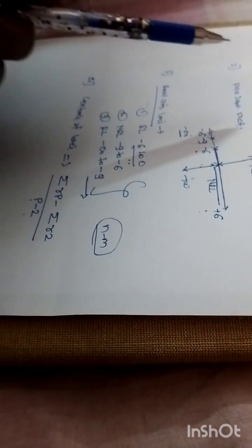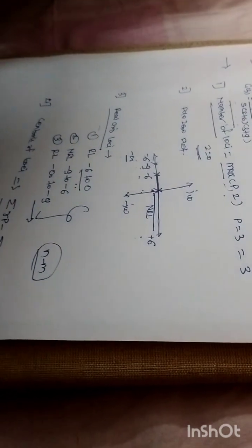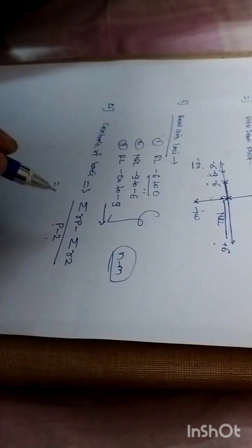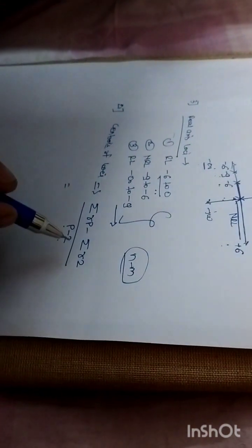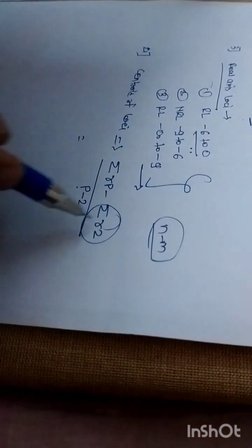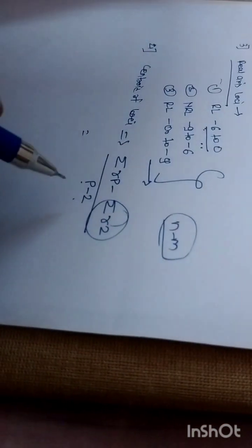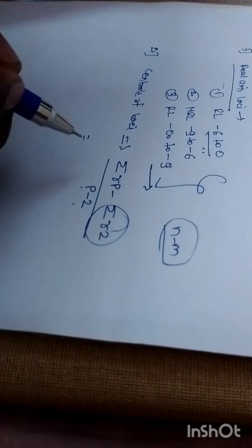Now currently in this example, this is the basic one. We don't have imaginary poles. We have only real poles, right? So this centroid will become what here? Summation of real part of poles minus summation of real part of zeros, as this term will become 0 because we don't have any zero present in this system equation, right?